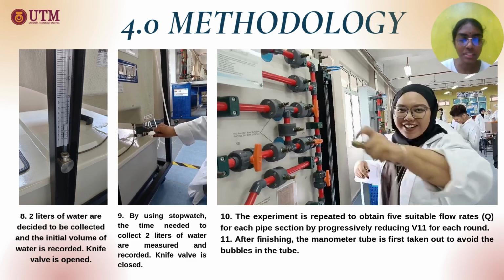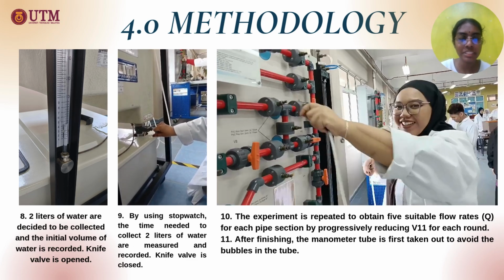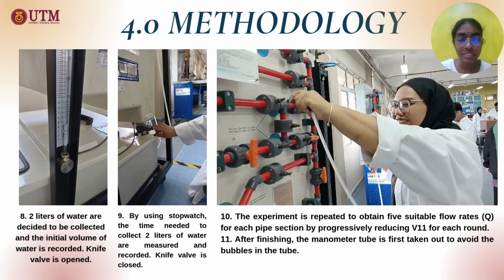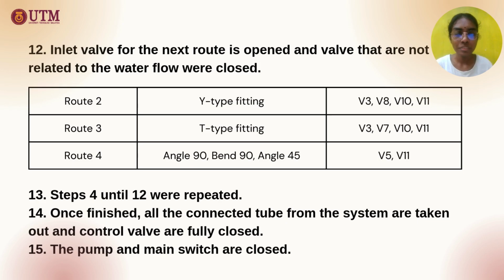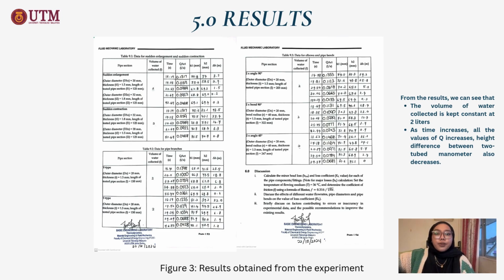The experiment is repeated 4 more times by progressively reducing valve 11. After that, we take out the manometer tube to test another component. Inlet valve for next route is opened and valves that are not used are closed. The experiment was repeated again, but this time with different component. Once finished, all the switches are closed. So these are the results obtained from our experiment.